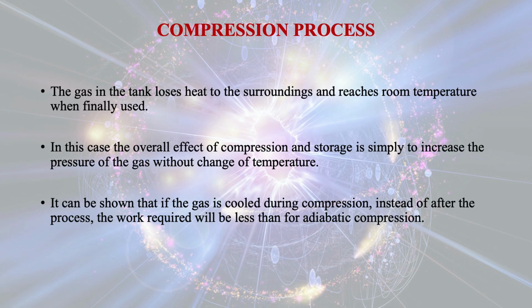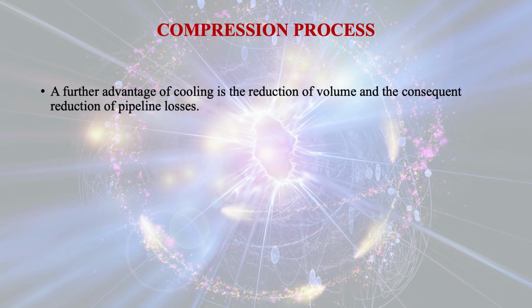It can be shown that if the gas is cooled during compression instead of after the process, the work required will be less than for adiabatic compression. A further advantage of cooling is the reduction of volume and the consequent reduction of pipeline losses.